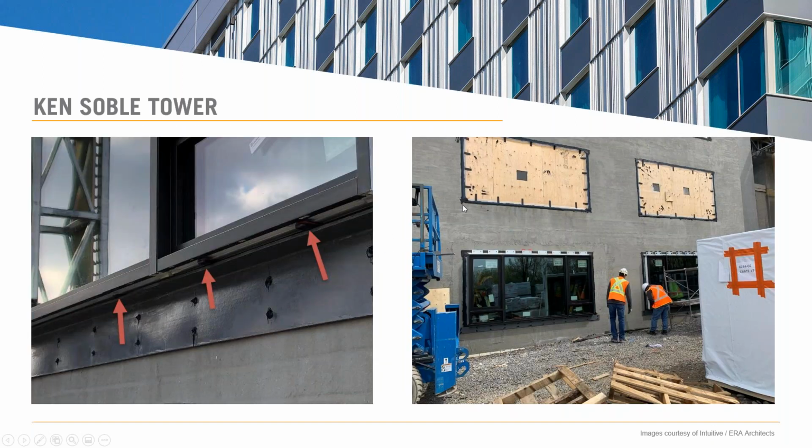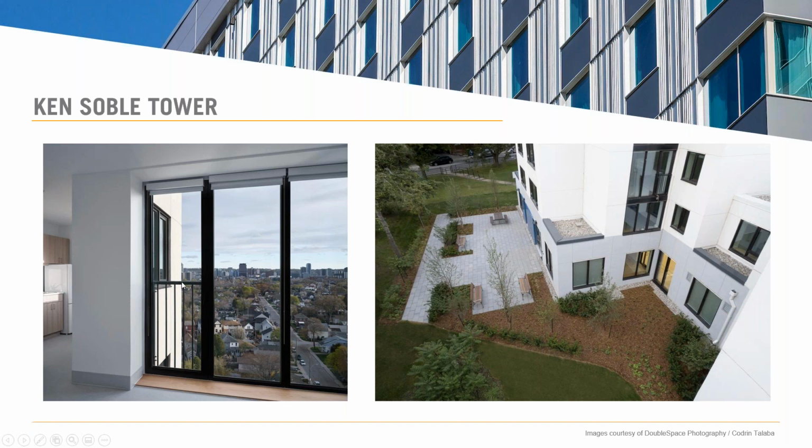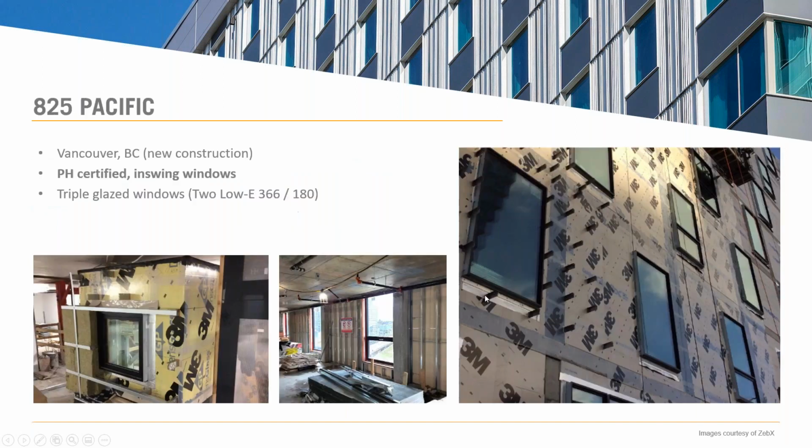And additionally, that concrete structure was exposed and just leaking heat. So in order to accommodate the exterior insulation, they had to move the windows very far out away from the structure and designed a low conductivity fiberglass support here to support the windows and move them out. So very fascinating. Here's a little image of that Juliet balcony. These are full openers, so they could fully open this door and get their little balcony outdoor feel with that. So very interesting project.